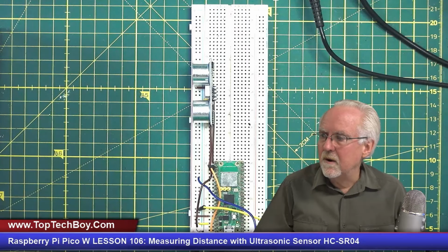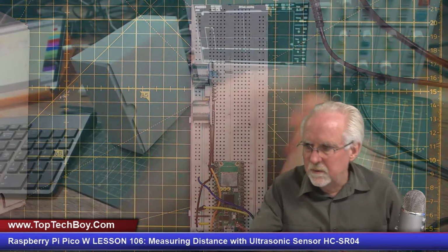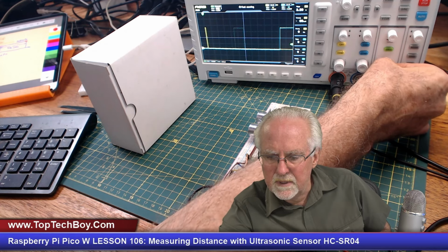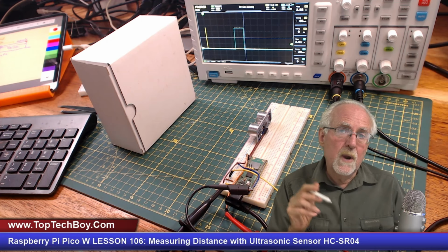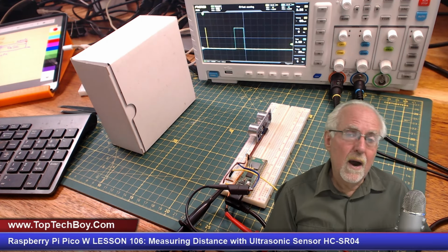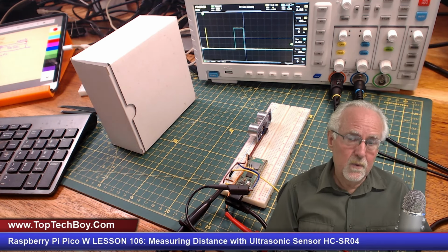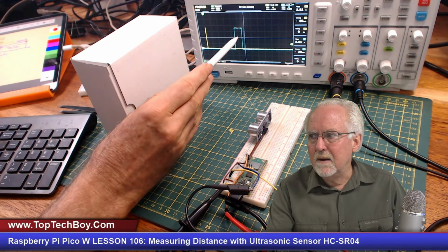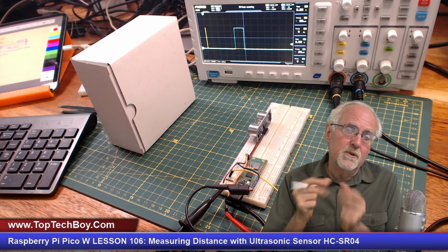And if we come back over here, let's shut this down back to where we can see our pulse. If you sit and watch this pulse, it's moving around, leading to errors in our measurement. Because why? We cannot trust MicroPython and the Raspberry Pi Pico W to do timing accurately. Right now when we're sitting here, it's kind of looking okay, but our code is really simple, not doing anything else.